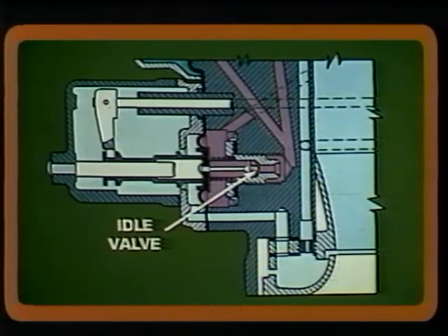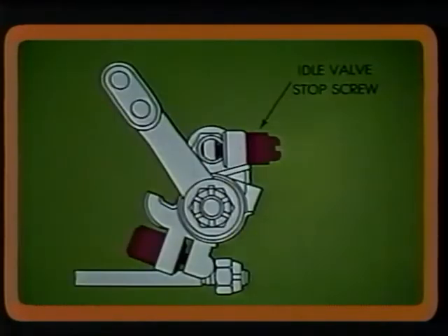When the throttle is closed for idling, however, all of the fuel that is discharged must pass through the nearly closed idle valve. This valve is connected by an adjustable linkage to the throttle air valve, so they open and close together. In this type of system, the idling RPM can be adjusted simply by turning the stop screw for the butterfly type air valve. The idle mixture is adjusted by the amount the mixture adjustment holds the idle valve off its seat.